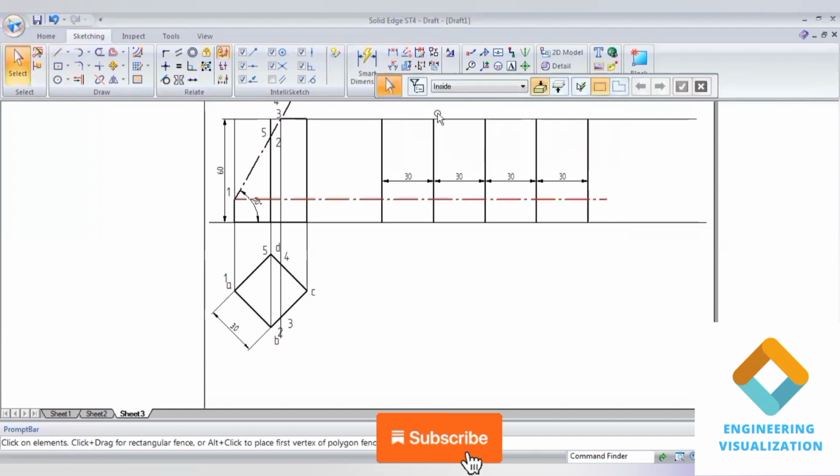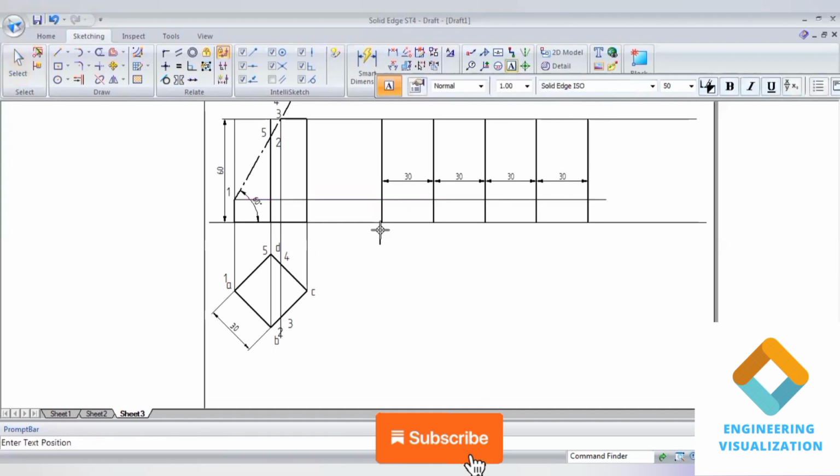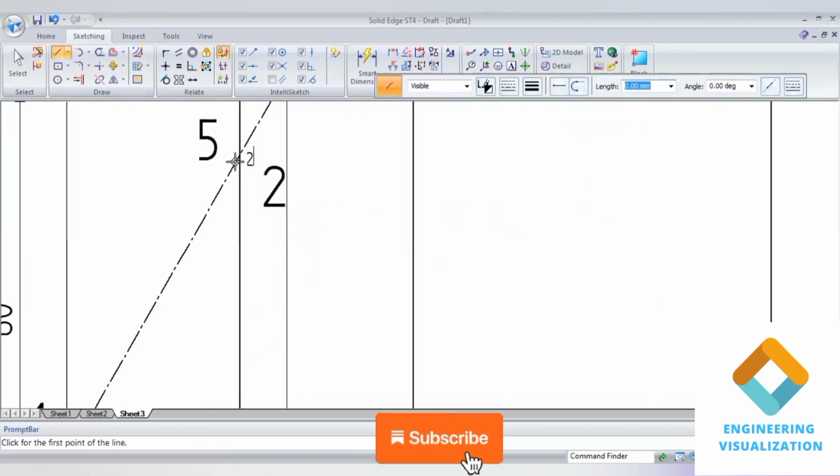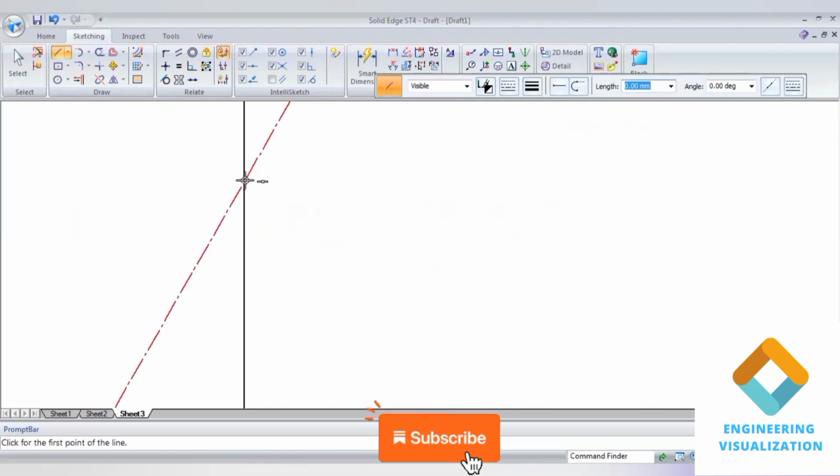Now by projecting from point 1, I am getting point number 1 on AA. First we have to write the namings A, B, C, D, A, so that indicates we'll get the exact vertical edges A, B, C, D, A. And now we can give the namings: 1 we are getting on the vertical edge A. And on the vertical edge B we have point number 2, that also we can project.